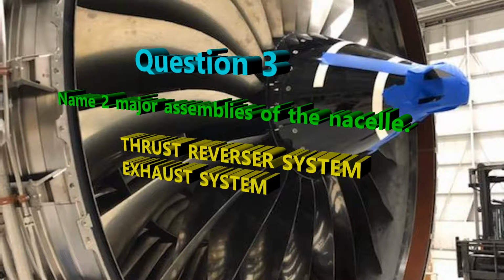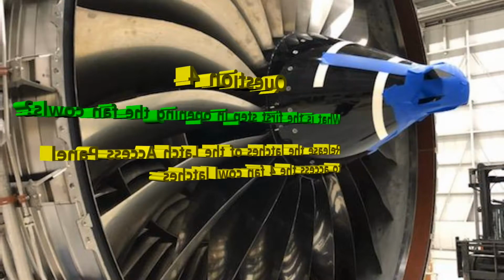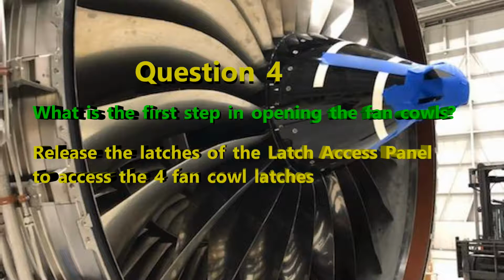Question number 4, what is the first step in opening the fan cowls? Is it A, press the opening button near the main landing gear and the latches will drop? Or B, release the latches of the latch access panel in order to access the 4 fan cowl latches? All right, it's B.